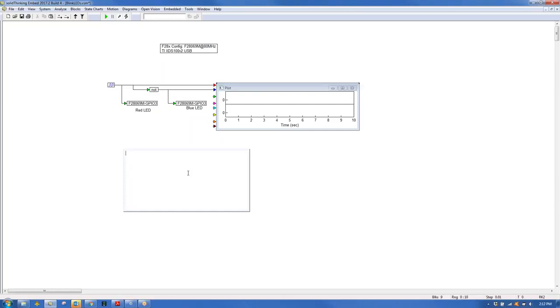Yes. So GPIO 34 is defined as the red LED, and GPIO 39 is defined as the blue LED. This is in the Texas Instrument documentation. You actually have to read it to discern this, but I'm just going to tell you that's what it is. It won't change. So if you're using these GPIO values, you will light up the red and the blue.